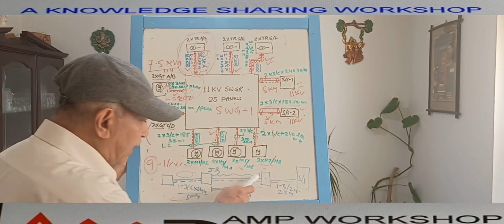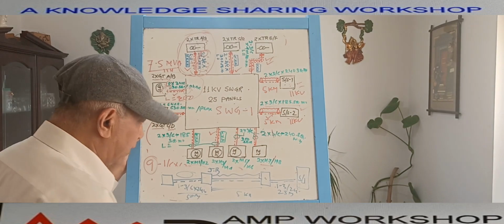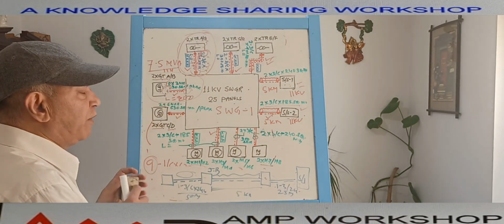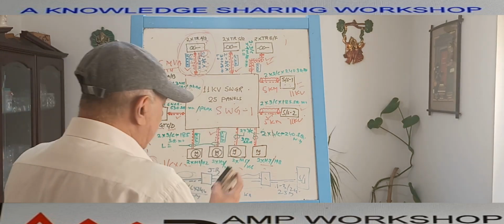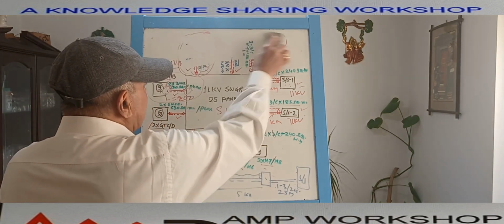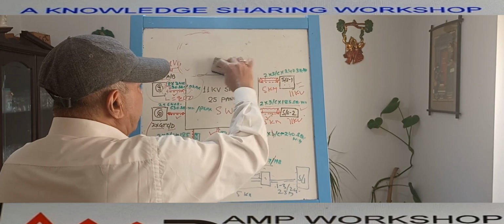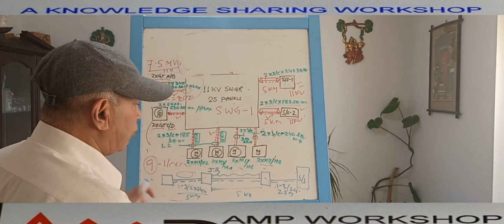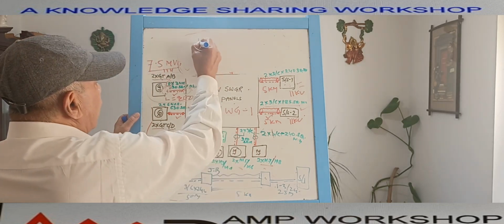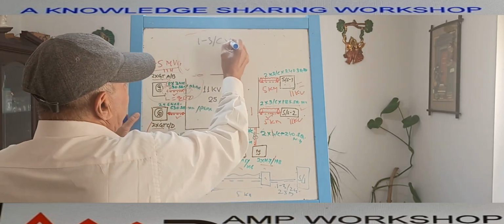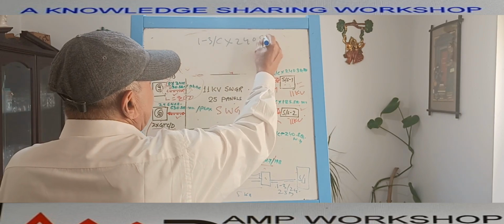So that means this subsea portion is only one cable, but that cable consists of three different parts. What are the three different parts? One part is a major power cable. That power cable, as we have already shown, is a 1 3-core into 240 square millimeter cable. That is one major power cable.